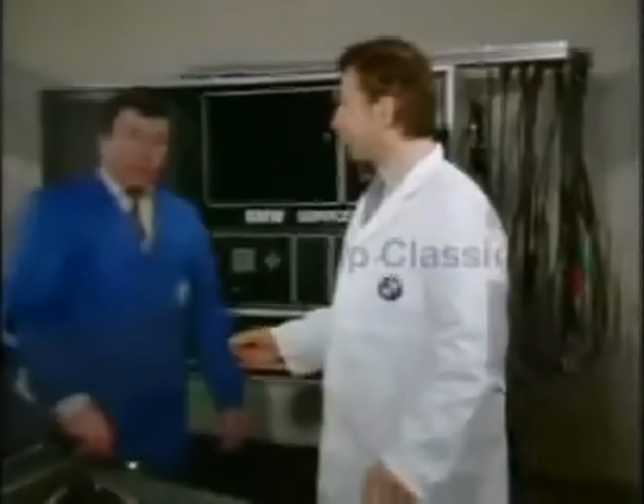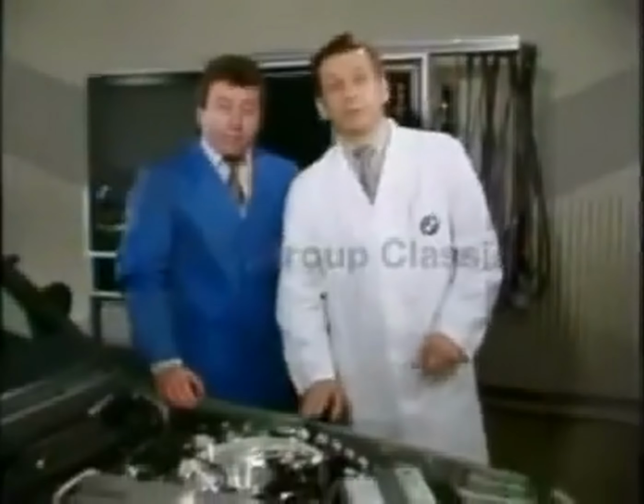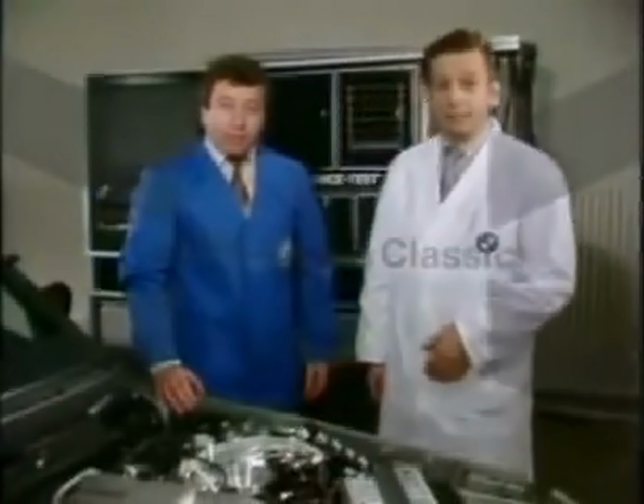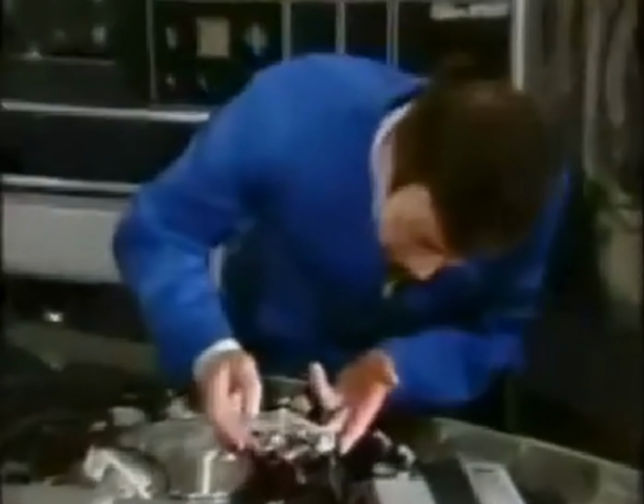Now for test and inspection procedures. Before starting work on the K-Jetronic, make absolutely sure that the engine is running well. Ignition and valves must be properly set, and the spark plugs must be functioning effectively. Exactly how the work is carried out on the system will now be demonstrated by our technician. Let's start with the fuel system. First, a visual inspection. We check all hoses and supply line connections for seal.